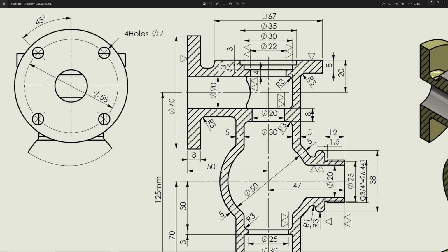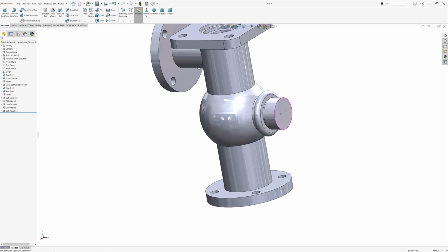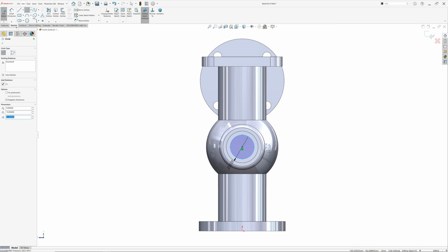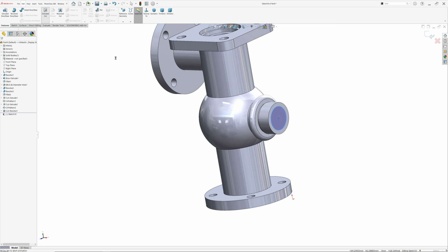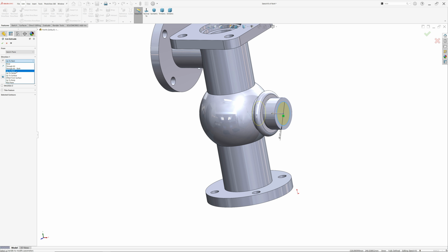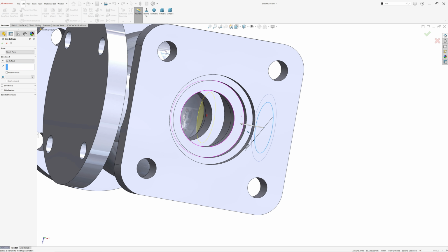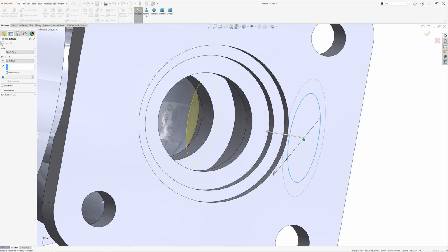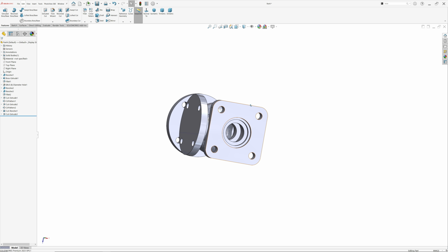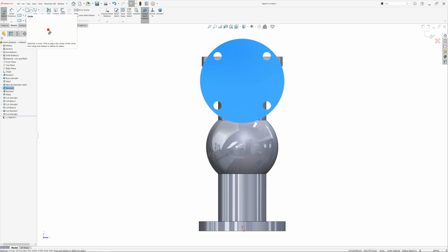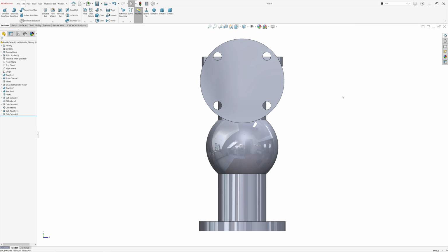So we will try. Let's select this face, sketch, activate hole, enter, extruded cut. Now for end condition, keep up to next. Up to next means, if I zoom, see this is going to cut up to the inside wall. Okay, similarly here, sketch. Okay, here I am going to discard.